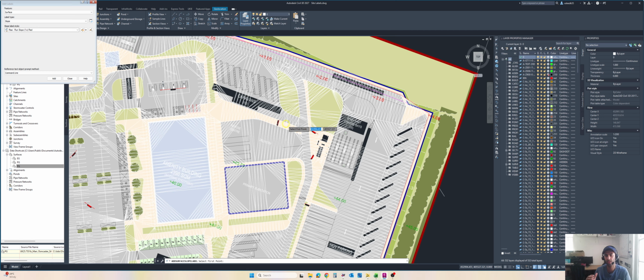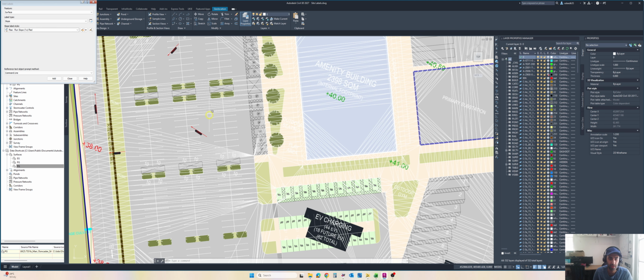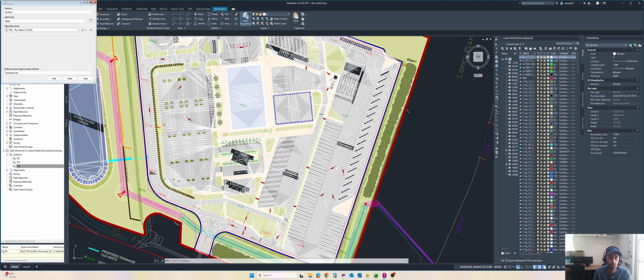If it's shallower than 1 in 2, for example 1 in 3, 4, 5, 8, it is a mild slope and we don't need any retaining walls for that. So we try to avoid retaining walls, because they are quite expensive, but we also have to design the project as well. So these are the basic ways to label the slopes.